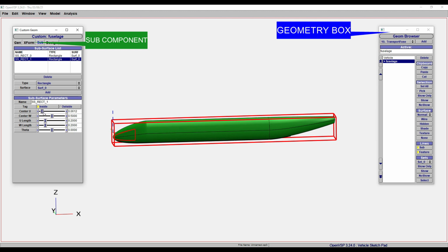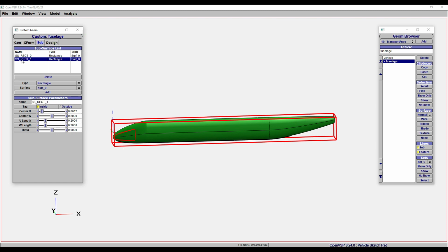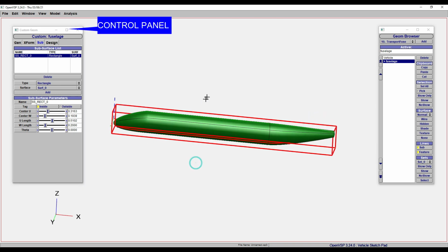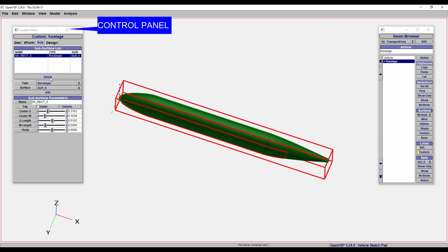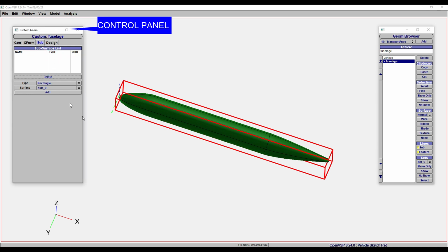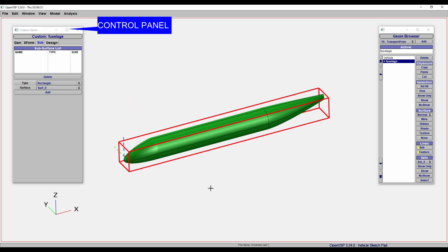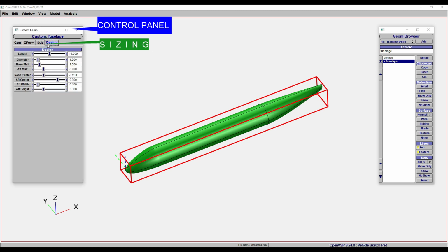If you want to show the cockpit, you can also make use of this. Okay, so this is a wonderful tab to highlight, maybe in a wing, to identify your control surface, and if you don't want it, just click it and delete. If you don't want any component, just select it and click delete, and that will go off.